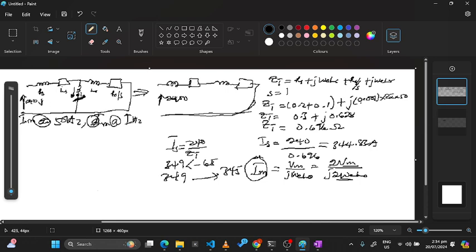Just use 1 hertz to find the inductance over here, the reactance over here. The reactance here is going to be very small because, did I actually do this? Ls, Rs. So the reactance here is going to be very small because it will be 2π times 1. Is that okay? It's very small. So we are going to ignore this.